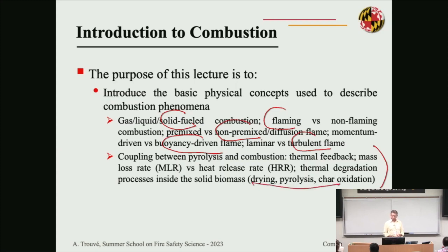I will, like Dr. Stolyarov, talk a little bit about what's happening in the solid phase, but not so much. That was more his part, but I will emphasize that in addition to pyrolysis, which is production of the fuel, you have also drying phenomena occurring inside the solid phase, and that's important. And you have also char oxidation, which is a dominant reaction for smoldering, the combustion regime without a flame, and I will talk a little bit about that.